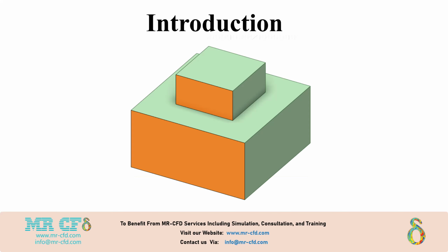In this session of SpaceClaim course, we are going to talk about the Offset tool and its applications in SpaceClaim software. The Offset tool creates a parallel copy of selected geometry at a fixed distance. In SpaceClaim, you can offset faces, surfaces of a solid or surface body, inflate or deflate the shape locally. You pick the entities, enter a distance, positive or negative, and SpaceClaim builds new geometry at that constant normal distance, either modifying the original body or creating new geometry, depending on options.